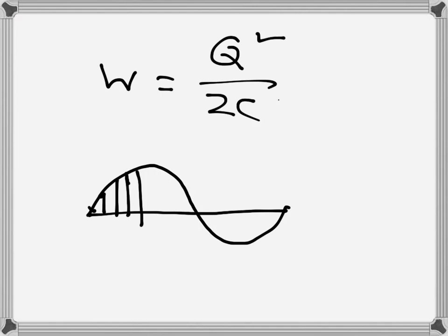However, the voltage is changing instantaneously, so the transient current will change also instantaneously, and before it decays there is another voltage that is coming up, so it cannot decay, and this way there will be a continuous current, because the polarity or the applied field keeps changing. And the current also takes the shape of the sinusoidal voltage, if it is a sinusoidal voltage, and the energy that is stored in the capacitor is alternately stored and then given back to the circuit when an AC is applied.